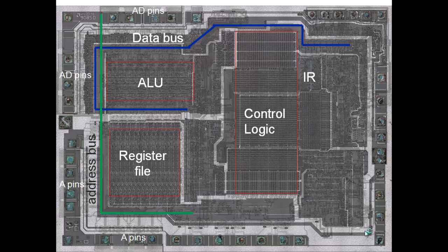It's a 40-pin microprocessor. And you can see the data bus in blue that I've drawn here. The data bus is running here, all this that you see here. This is similar to the one that we just designed. We had an adder subtractor block. It has an ALU, arithmetic logic unit. It can do addition, subtraction, AND, OR, different kinds of logical operations, shift right, shift left, and all that. So this is the ALU that you see here.